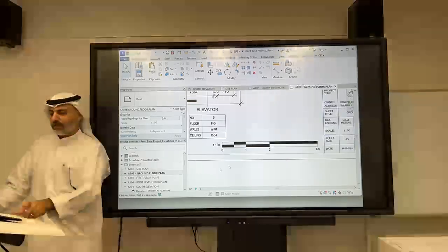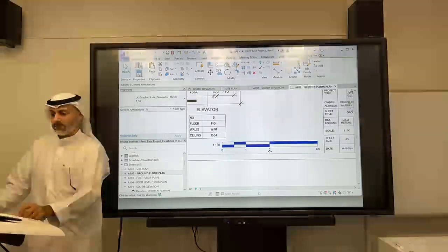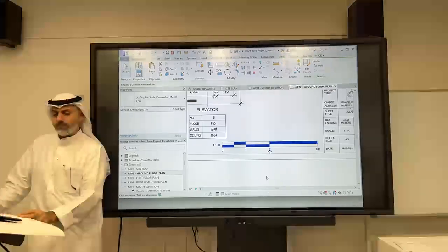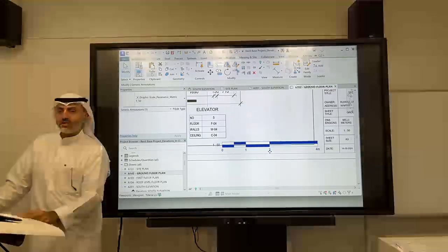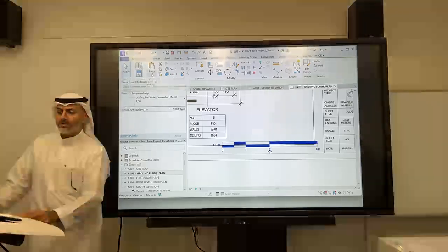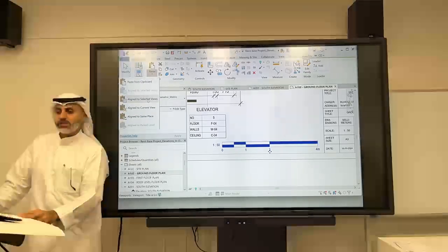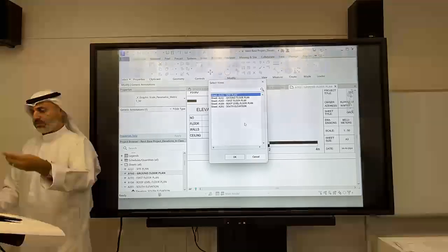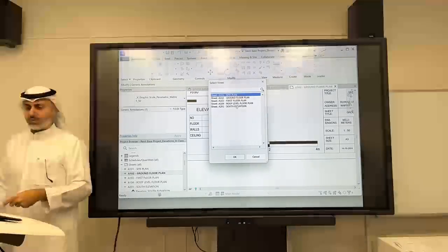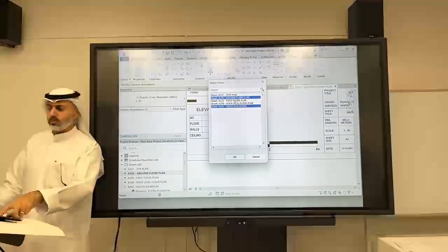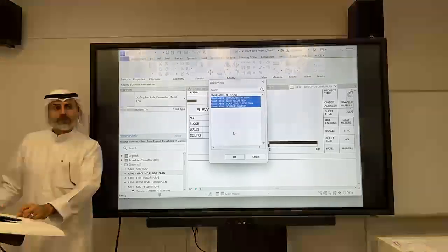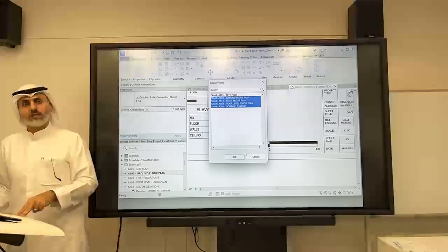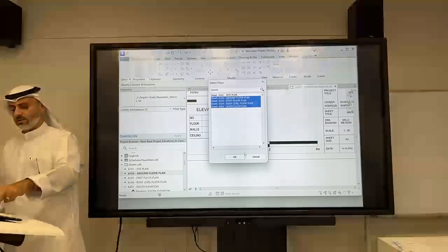Okay, I'm in my sheet, I select the scale bar, Control C. Then in the paste under clipboard you do the drop down arrow and you say aligned to selected views. At this point you probably should have deleted all your other scale bars and then just check all of the new views that you want to paste it in. When you hit OK, it's going to paste it in the same exact spot in the sheets. So this way it's going to be neat throughout.